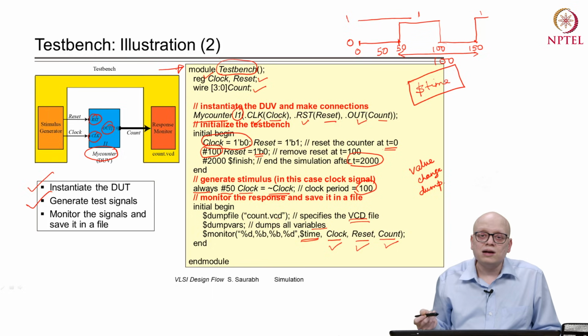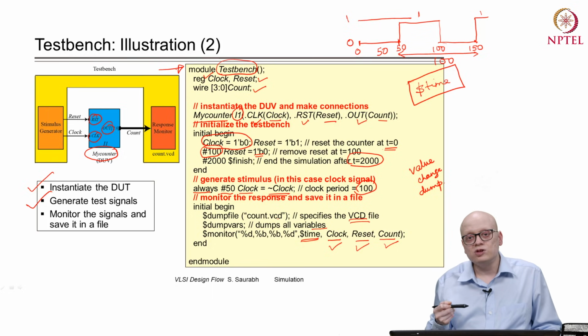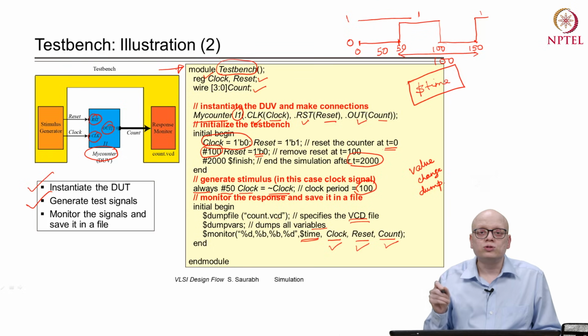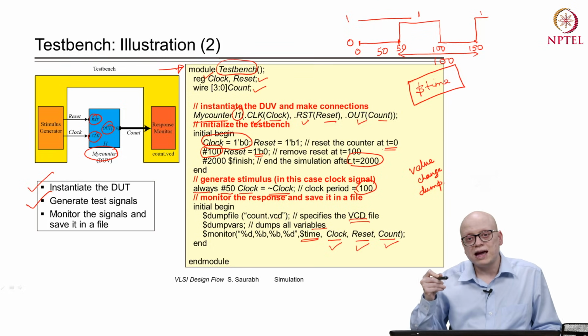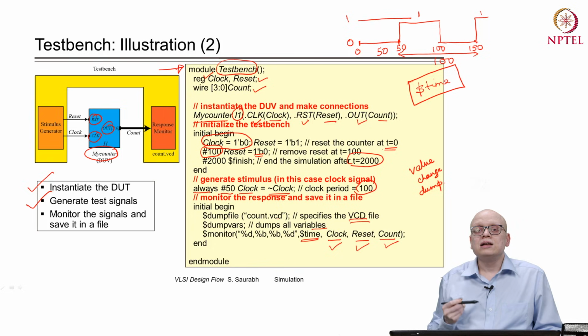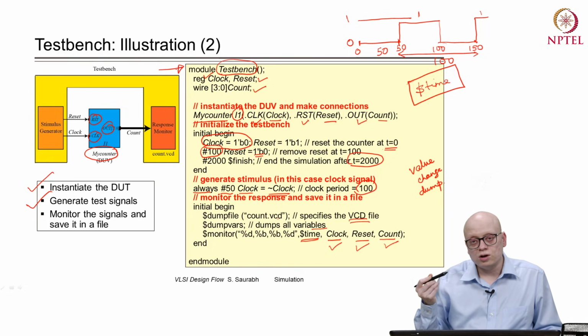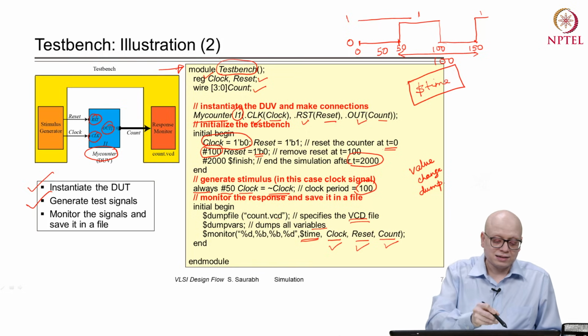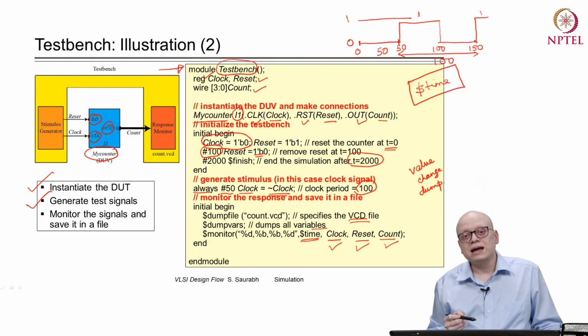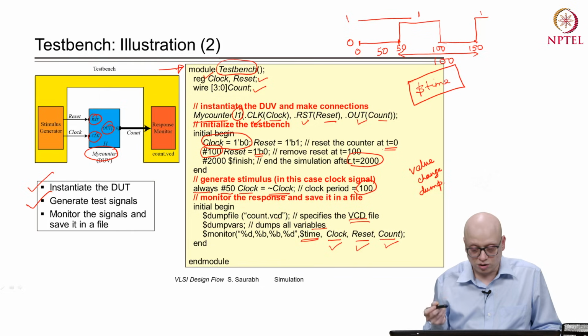Then we can load the VCD file in a waveform viewer and see the values of the signals at various time instants, and by observing the response we can make sure that our design, in this case the counter, is working as per expectation or not.